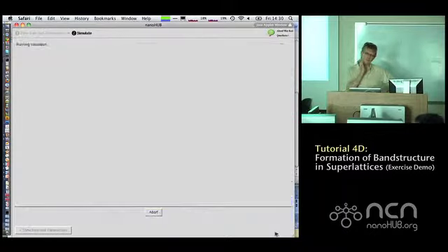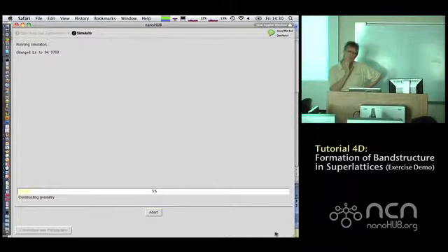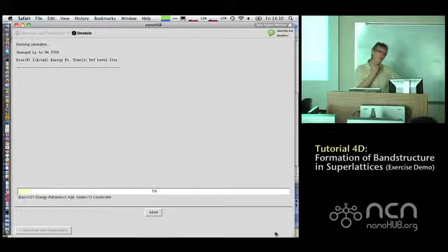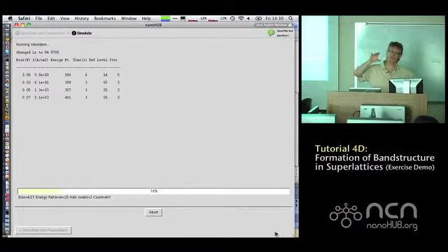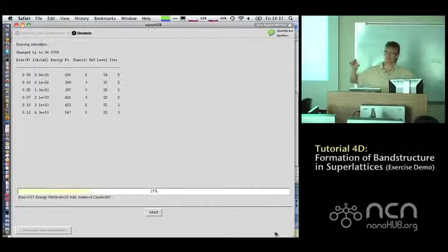And I hit simulate. It's going to take a little longer to compute, but what it does now is, previously it calculated the charge semi-classically, and then did a one-pass non-equilibrium Green function calculation on top of that. Now, it calculates the NEGF, gets the charge and the current, distributes the charge across the device, recalculates the potential, calculates the NEGF, so it needs to converge a little longer.